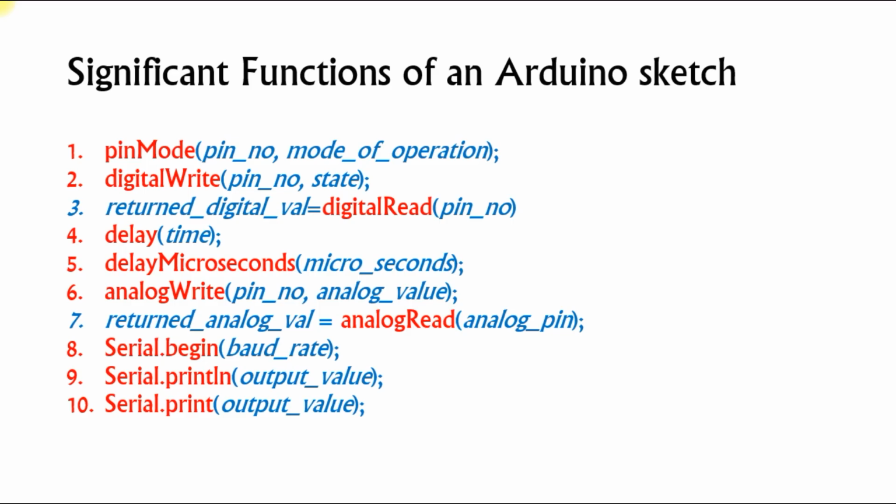If you want to print the data in that serial monitor, you need to go for the class called Serial. Take that Serial class, and within that you can take the command print or println. Just send the data. If you send it within double quotes, it will be considered a string, and the string will be printed. If you send it without double quotes, it will be treated as a variable name, and the value behind the variable name will be printed.